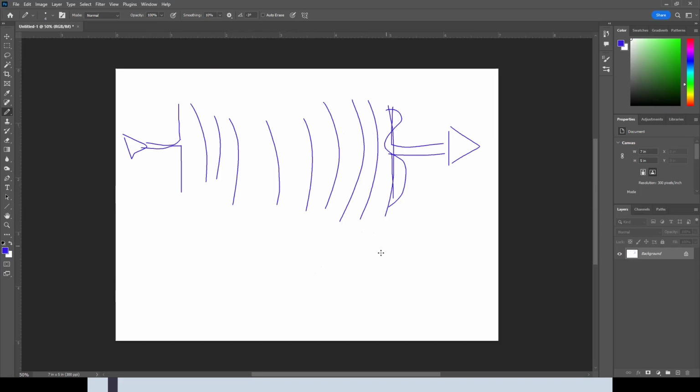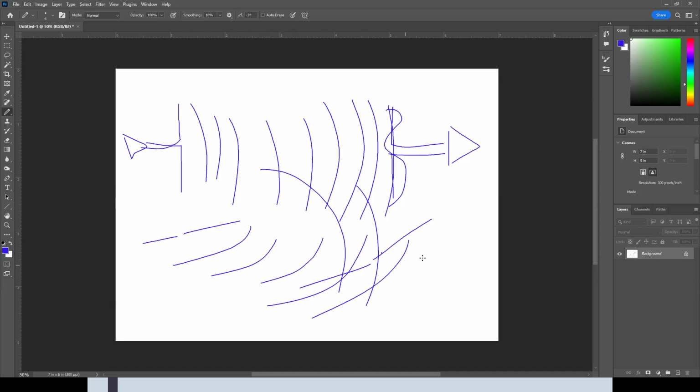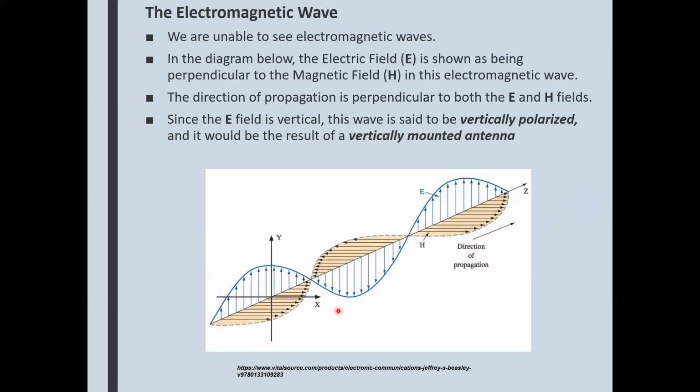In the same way, if you polarize the antenna vertically, you can actually lose the transmission. So in that case, you need to have a horizontally polarized antenna so it transmits the E fields that way. And of course, the magnetic fields associated with that would be perpendicular to that. So yes, it's important how the receiver antenna is positioned with reference to the transmitting antenna.